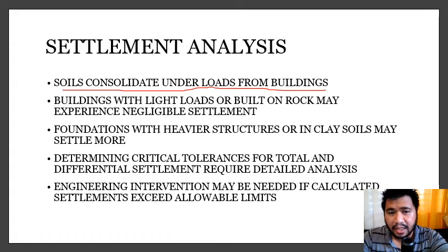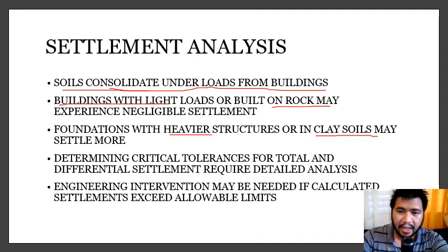If you have light buildings or your subsurface is competent material, you might not get a lot of consolidation settlement. Now, if your structure is relatively heavy or your underlying soil is clayey or saturated clay, which typically is more compressible, you may get more settlement, consolidation settlement to be specific.